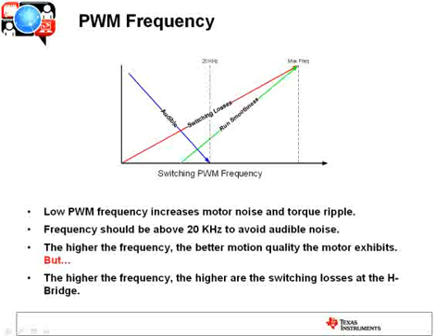So in terms of the PWM frequency, there's a couple trade-offs here. The first is, in an ideal world, you want to get the PWM frequency out of the audible range. And that's simple enough in terms of the reason you want to do that: if it's in the audible range, you can hear that. And you can see this in some of the legacy motors that are using the switching frequency where they're, say, 15 to 16 kilohertz. You can actually hear the switching frequency of that motor. So if you can get it above the audible range, you're going to cut that noise out.